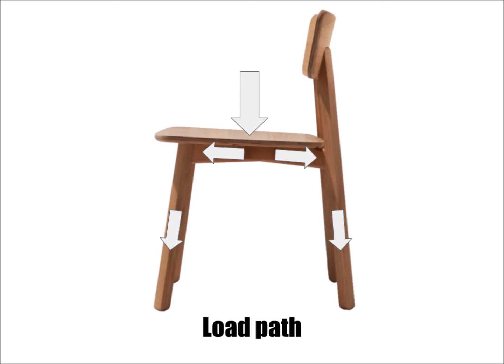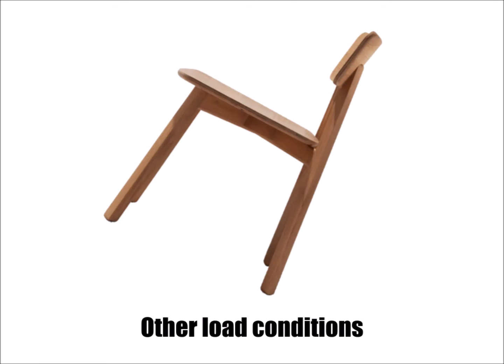We see here that the forces are handled initially by the seat, which has braces to transfer the load to the corners where the legs are. Finally, the legs are pretty much straight down to the floor. Not terrible. But we have to consider non-standard but foreseeable load cases where failure would still be unacceptable.